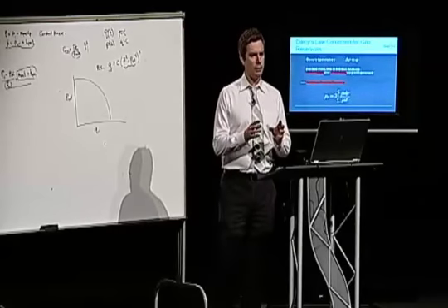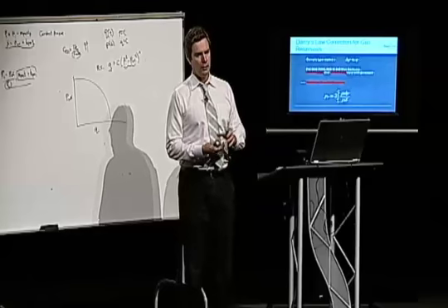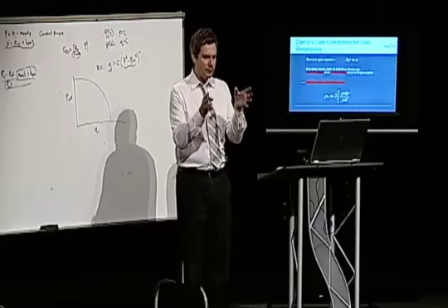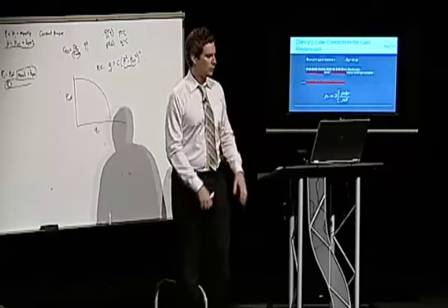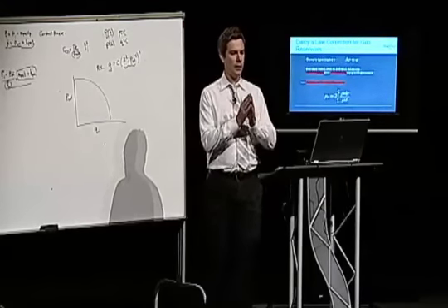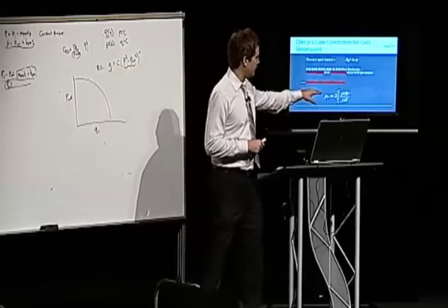P squared is a pretty good approximation as long as the pressures are quite low. When the pressures get up into the higher regions, it doesn't work as well. So it has a limited range of application. So what we prefer to use instead is pseudo pressure. And pseudo pressure will solve this problem for any range of pressure and temperature. And it's an exact solution.